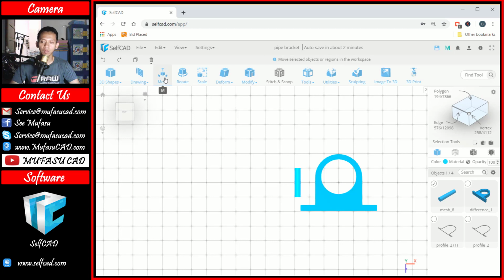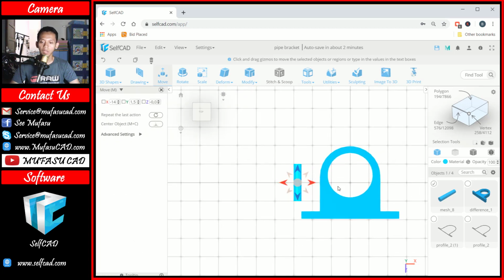And I will move this object to the right. You can click the move command. I will move in the right axis in here. Okay, I will set into minus 10,5. Okay, 10,5, and then I will copy this object.